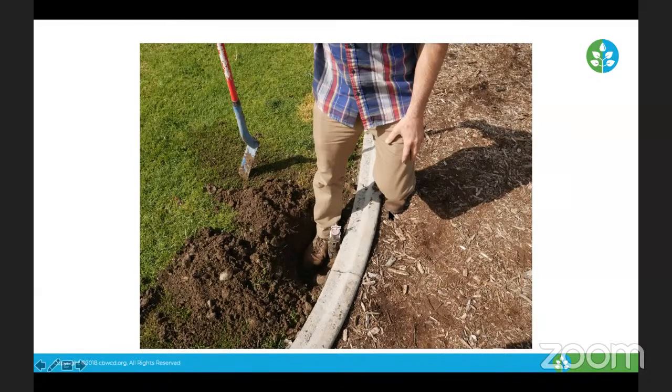Another way you could do this repair, which I've done in the past, is to get construction sand and put it at the bottom to about halfway up on this sprinkler repair, because you can really compact it, and it'll make sure the sprinkler won't tilt again.